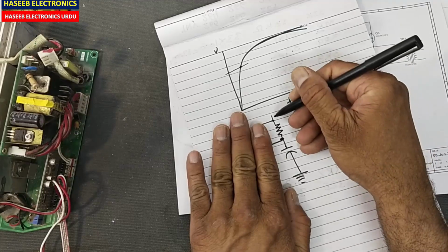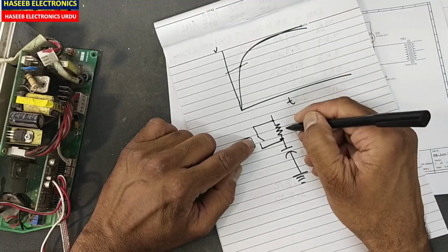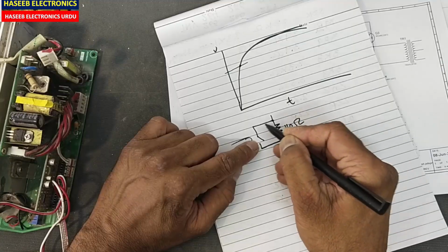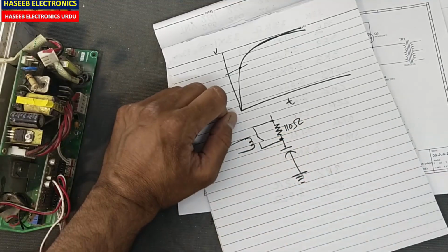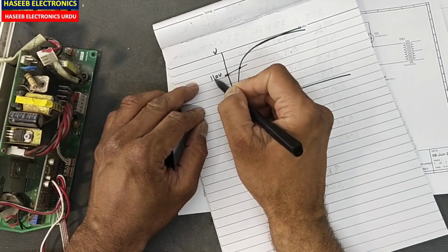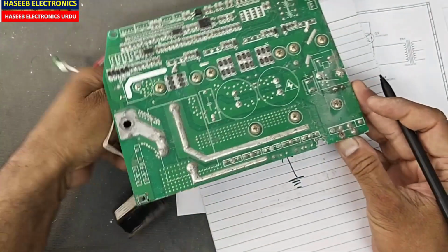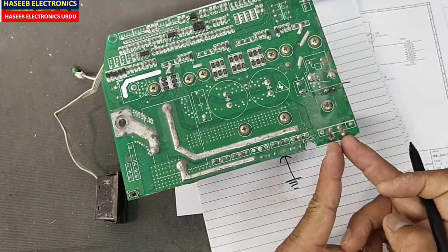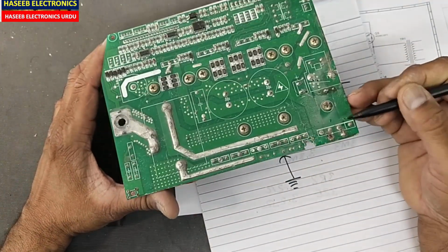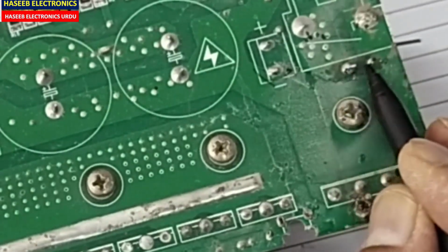Normally the current will pass through this resistor. When this relay is turned on, here if we have 110 ohm for example, and here we have 0 ohm resistance, current will select the easiest path. Now we can say at this point we have 100 volt DC, because our bridge rectifier is providing DC voltage. It is taking AC voltage here, the direct AC line voltage, and it will provide DC voltage. This is our positive terminal, and the positive terminal is connected to this component that is here.